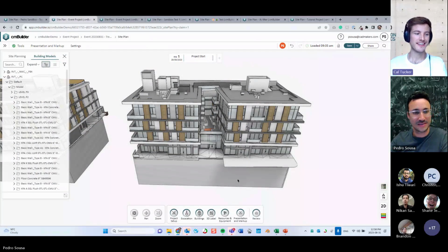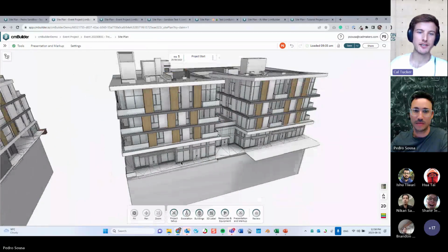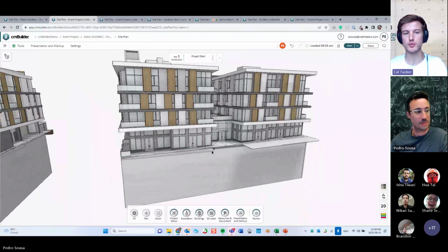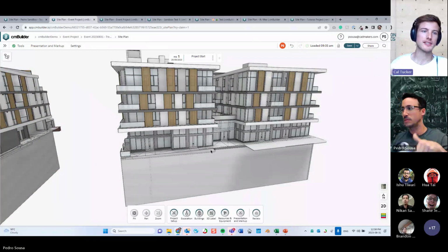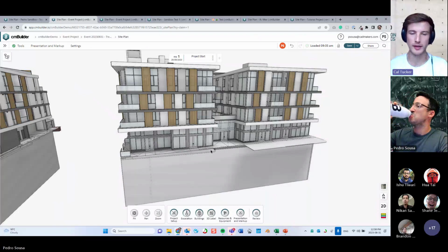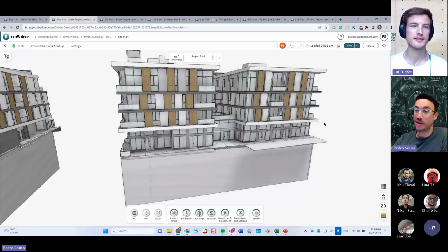There's also one other that I was hoping you'd mention. Another good reason to use IFC over FBX is that a lot of structural engineers or architectural engineers won't split things by level. Let's say a column, for example, would extend all the way from the bottom of the parkade up to your 20th floor, which makes it really difficult to sequence, whereas IFC has a checkbox when exporting to split vertical elements by level. From Revit, right? So when you export it from Revit, you can do that.